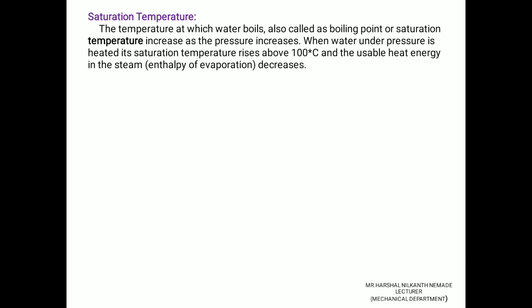Saturation temperature. The temperature at which the water boils, also called as the boiling point or the saturation temperature, increases with the pressure. When water under the pressure is heated, the saturation temperature rises above 100 degrees Celsius, and usually the heat energy in the steam, the enthalpy of the evaporation, decreases.